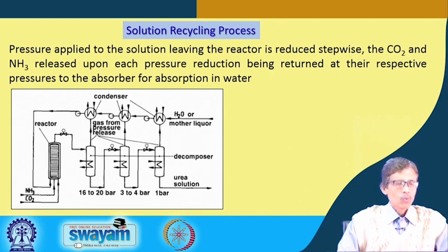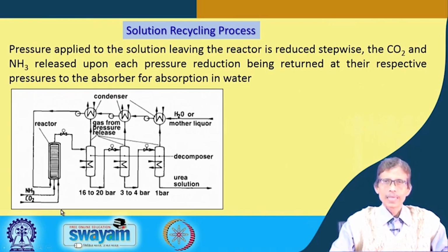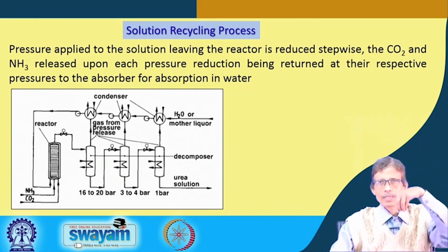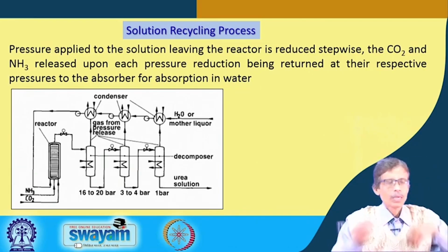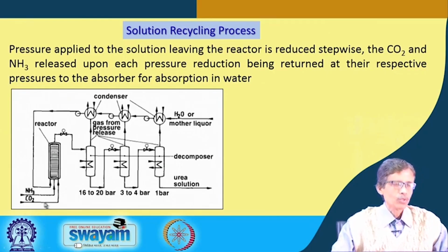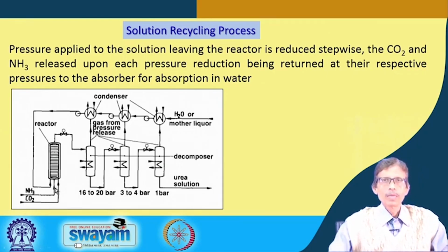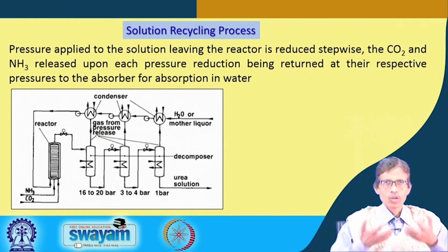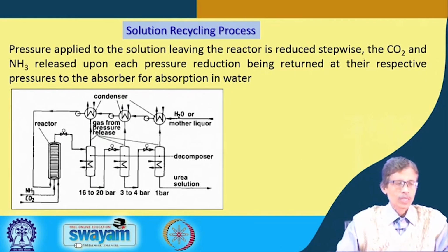So, since ammonia and carbon dioxide are both gases, compared to several previous techniques which we have seen, such as making ammonium sulfate, where the acid is put from the top and gas from the bottom, here we are putting both NH3 and CO2 from the bottom of the reactor, because both of them are of gaseous origin. So, during the reaction, this is basically the valve, you have the corresponding flow meter, and you know the internal pressure of the gas, because we should always monitor the internal pressure of the reaction chamber, so that the pressure does not build up such that there can be an explosion.